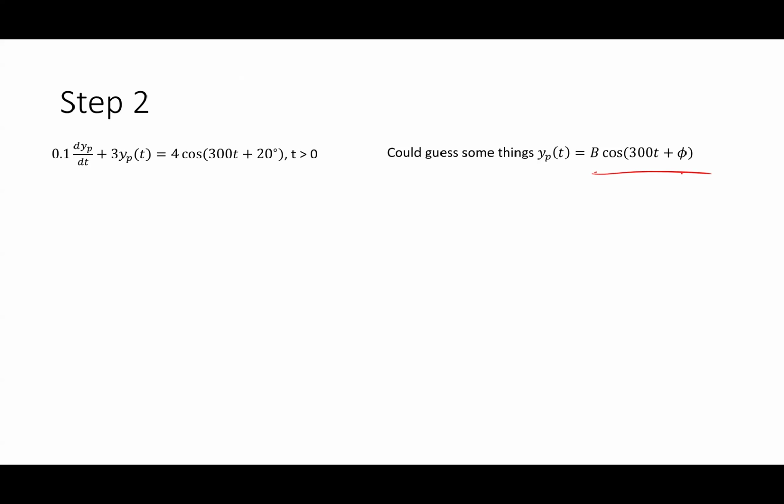If that's the case, it turns out to be really handy because it means that all that I'm going to need is b e to the j phi, which is a constant number. All right. I can simplify things a lot. I can get rid of the t part, which ultimately means I can get rid of the derivative part. That's where the stuff becomes really useful: every circuit you ever solved would be differential equations based if I couldn't use complex numbers to represent these guys.